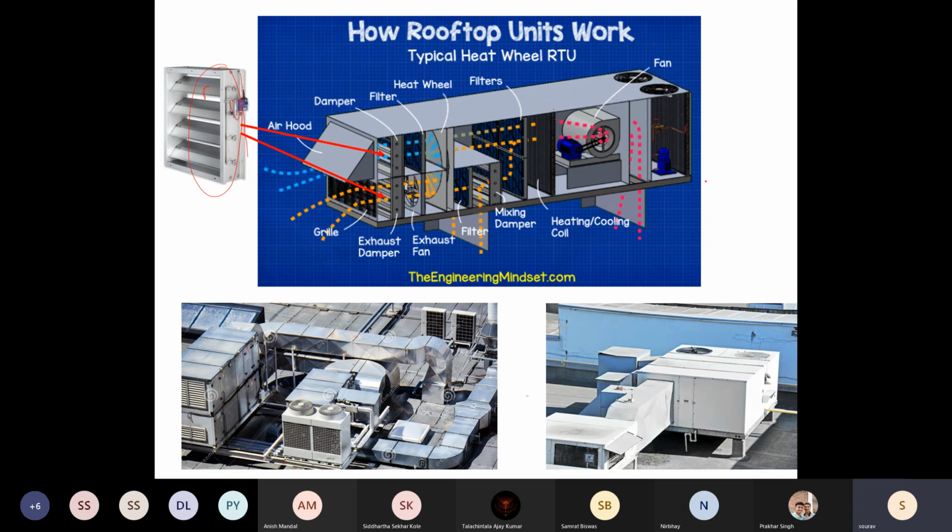This kind of a system is good enough for a few hundred tons of load, but when it comes to close to 1,000 tons, you can have a separate configuration where you do not have to make your roof very strong because you have to withstand all the vibrational loads from the compressor, the static weight and everything. So you can remove that cost from your construction. You can keep your refrigeration system if you have space on the ground level.